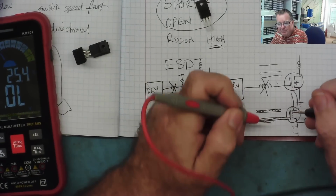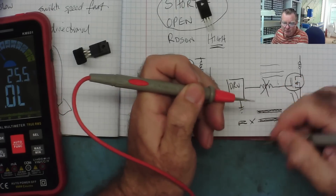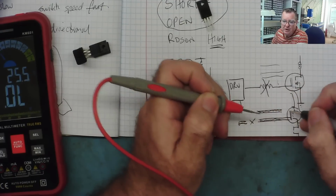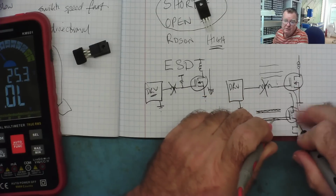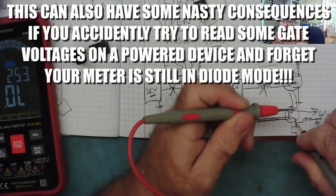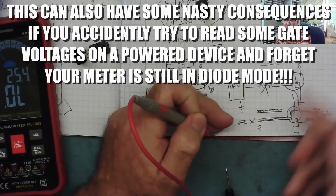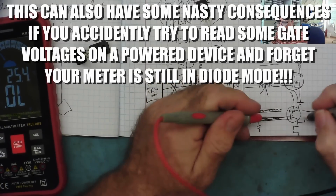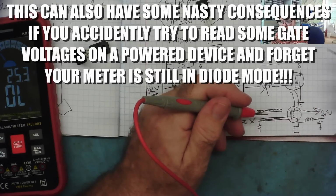But you should not be able to do that with a MOSFET in your circuit connected to a pulse width modulator. Because unless this gate is open circuit, when you apply some voltage to here, yes, maybe this is switched on. But once you remove the voltage from your multimeter, the resistor, which is effectively connected from here to ground, will discharge the voltage and the MOSFET will switch off. So you should not be able to turn on MOSFETs in circuit like I was just doing out of circuit.